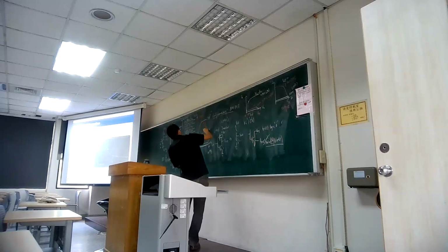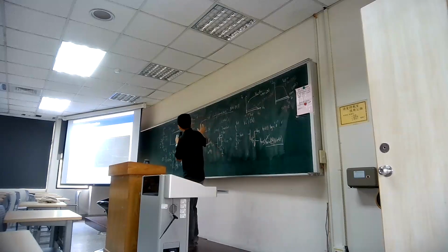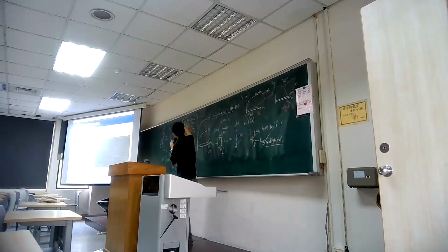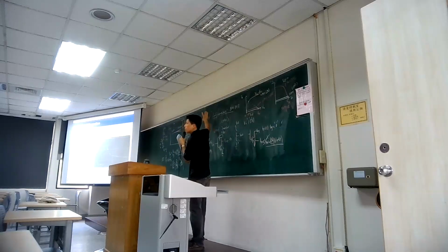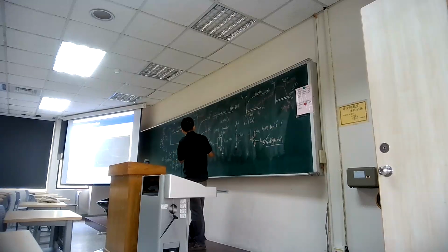And how about if you use 2 volt in VGS? You get minus 3 volt. Here's minus 4, here's minus 3. So the solution with this curve will jump from here to here. Okay, so you can always connect. What we do here is separate the NMOS and the PMOS corresponding to the gate to source voltage, and by this you plot the curve for both PMOS and NMOS.